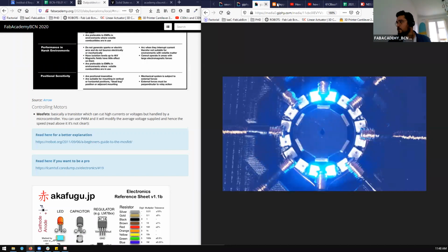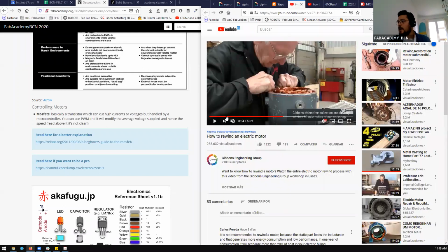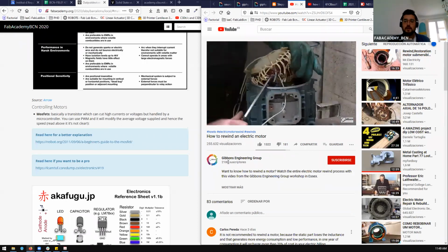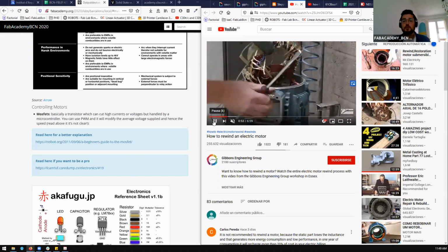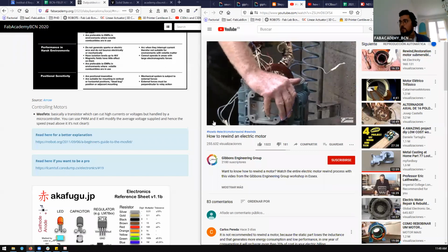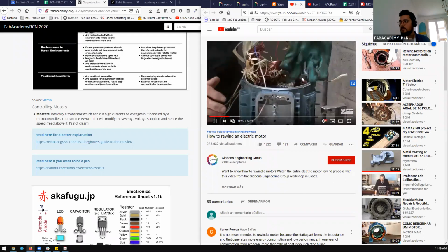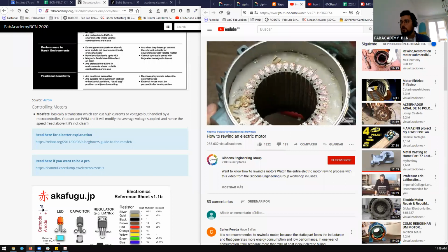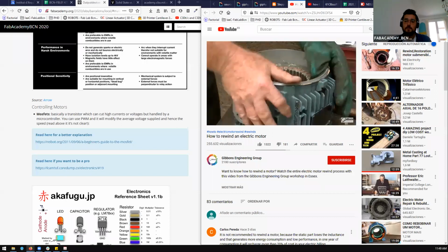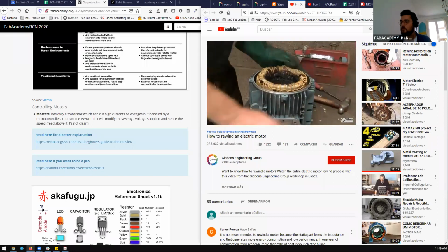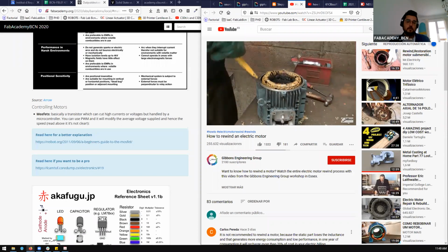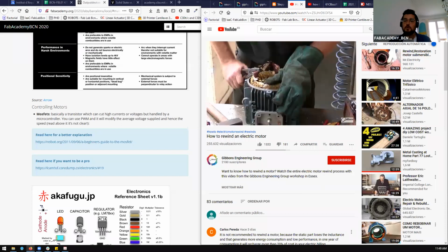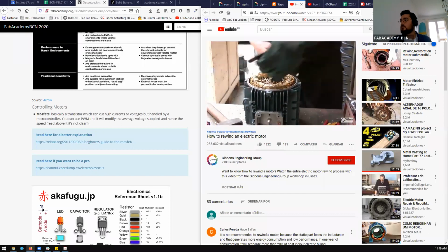And there is where we come, for example, to the DC motors: rewinding the motor is something that is really common. Usually, for example, with all swimming pool motors, you never buy a new one. What you do is open up, disassemble and replace the copper, because by the friction and the time and the heat produced, the copper gets wasted, gets burned. That's why, when your community has a swimming pool, they say the swimming pool is broken. Why? Because the motor needs to be replaced because it has burned down because of the heat dissipated by the motor itself. And this is something really common in industrial motors.